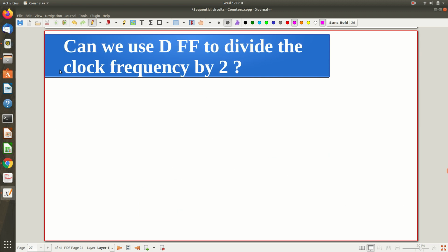Now we constructed this using a T flip-flop. Now the question is, can I construct the same circuit using a D flip-flop? Okay, and let's try that. So what is our D flip-flop? T is toggle mode or retain mode, but D means whatever be your D, that will come in the output Q, and there is a Q complement also, right? So what I can tell you is, you take this Q complement and you connect it with this D.